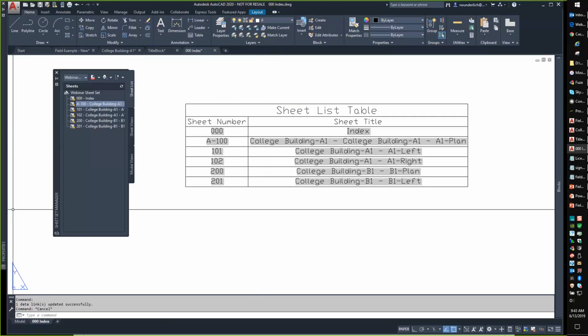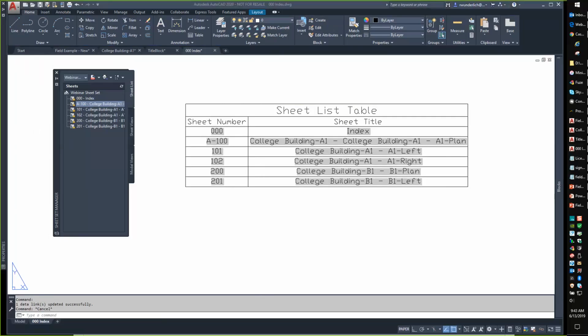Let's see, will all of this work in AutoCAD LT? Yes, it will. AutoCAD LT supports all the same functionality as regards to fields and sheet sets. The only difference is you will not have options in LT in order to find Lisp expressions and Lisp information.